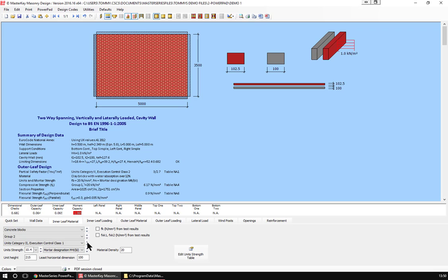As you can see, as we start to reduce it down to the more basic category 2, then we have 7% overstressing. So that's not going to solve my problem. I would probably let that go and say it's deemed to satisfy, it's less than 1% overstressing, and no checking engineer is going to fail you on that. But the choice is yours.